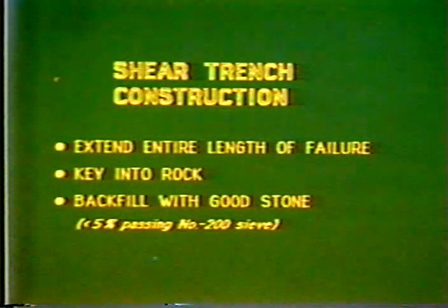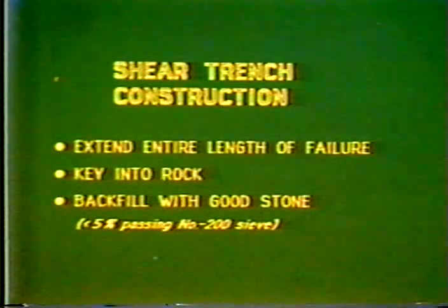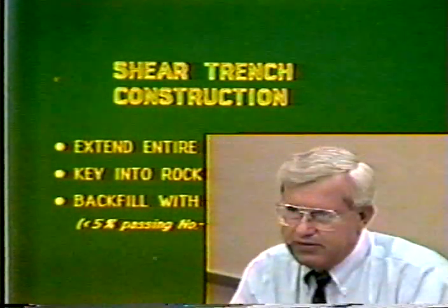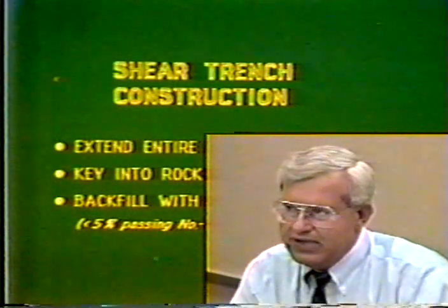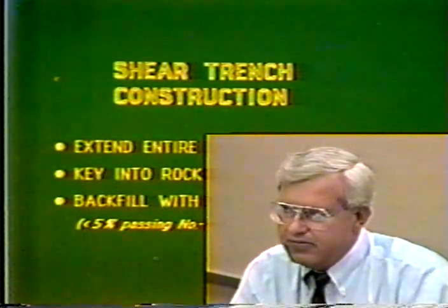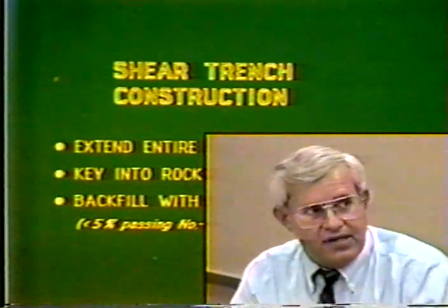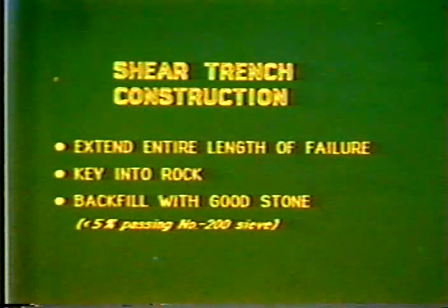It needs to be keyed into rock. But let me make one comment about that. Keying it into rock is always desirable, but sometimes if you get it deep enough, you can force that failure plane deep and long. And when you do that, you increase the stability or you increase the safety factor. And of course, the third thing there is that you've got to backfill it with good stone.